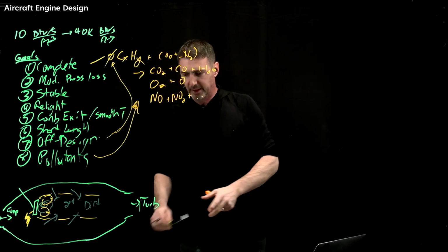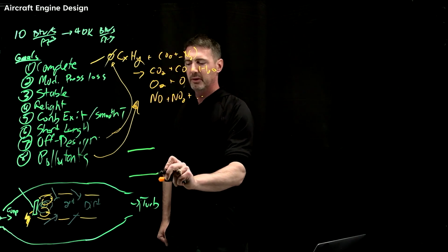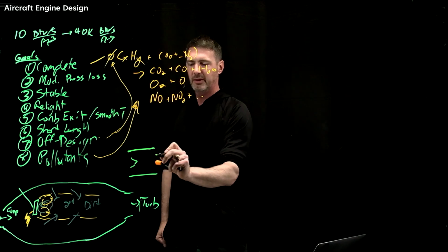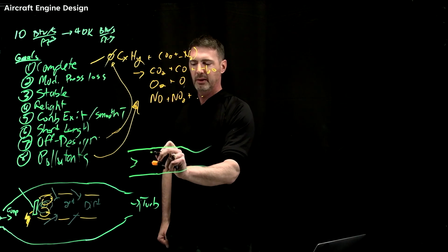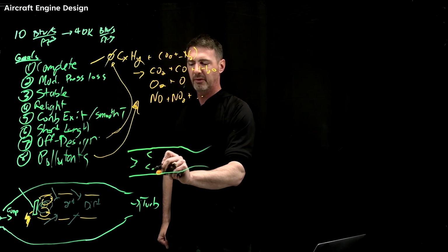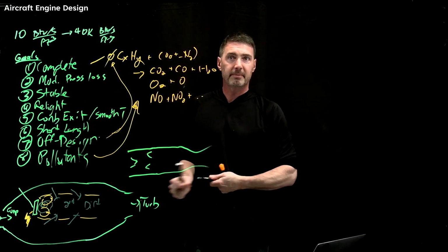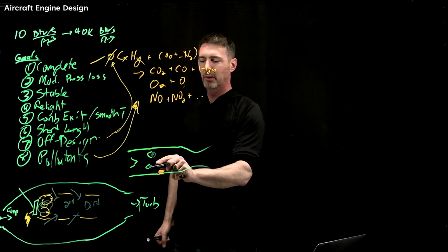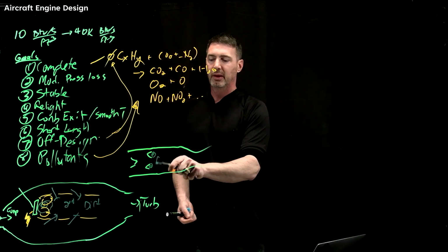Now, if I draw an afterburner, right? So the end of your jet engine. Here's your jet exhaust. You then can have an afterburner channel. We've drawn this before, and usually you have these flame buckets. The same sort of thing is going to happen. This air is now still hot, and so by adding fuel, you can get it to light. Effectively, you're adding fuel, it auto-ignites.